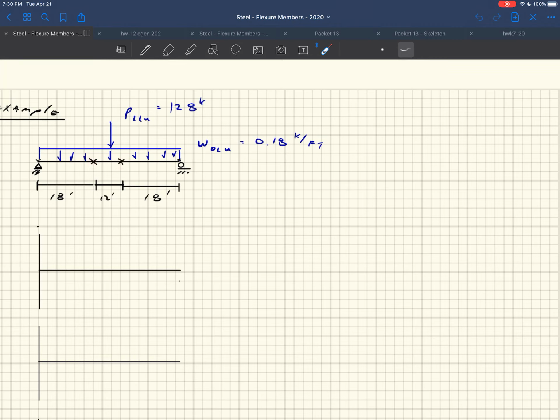So they're not going to affect your deflections. They're not going to affect your moment and stuff like that. They are just there. They matter when it comes to looking at lateral torsional buckling. Okay. I think your homework problem has you calculate deflections. Well, the deflections will not be a factor of these lateral supports, right?